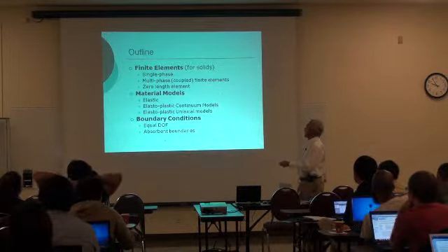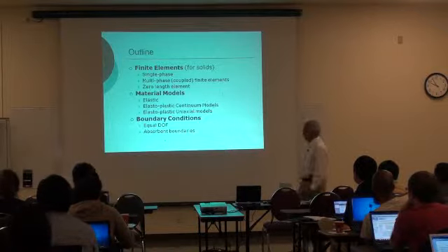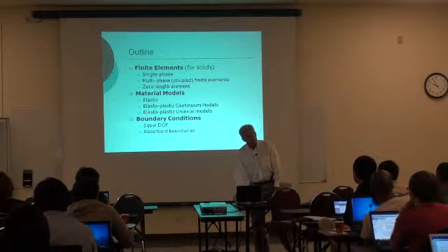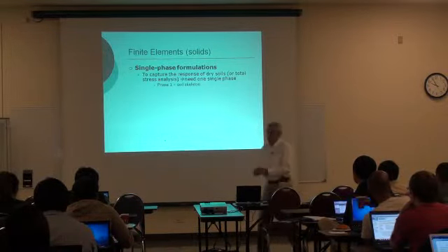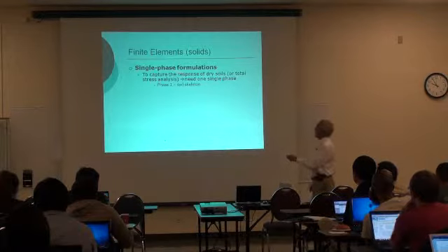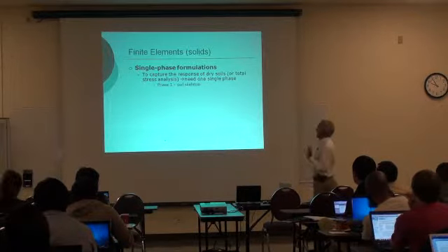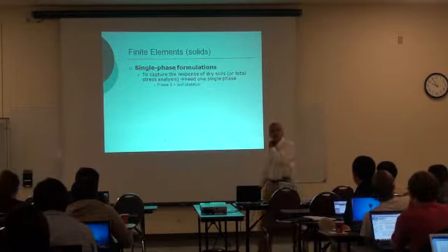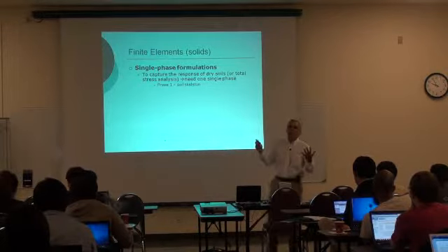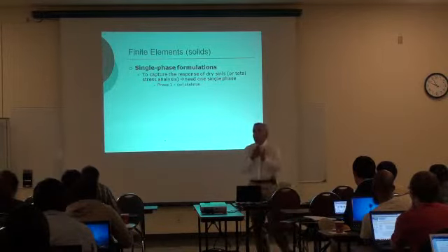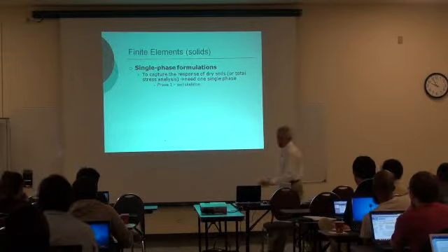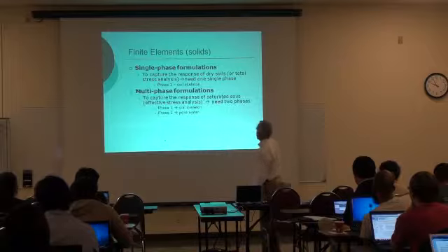And then for the boundary conditions, we will talk about equal DOF and how to address the problem of absorbent boundaries. For the finite elements, the single phase formulations capture the response of dry soil, or are used for what is called total stress analysis, where I don't need to separate the soil and the water. We look just at the behavior of the soil, dry soil or total stress analysis. Only one phase, which is the soil skeleton.